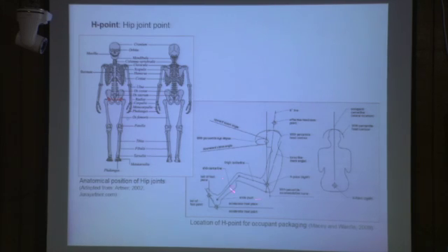In a sitting posture or workstation, where the task requires a seated posture, first you have to give the appropriate sitting posture to the digital human model. After that, you have to position the human model on the seat in relation to its H point.